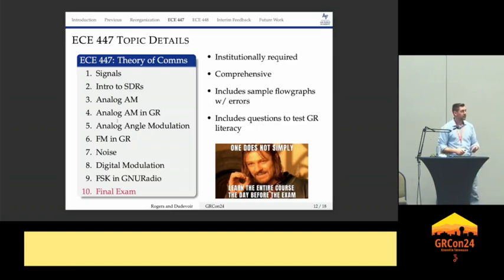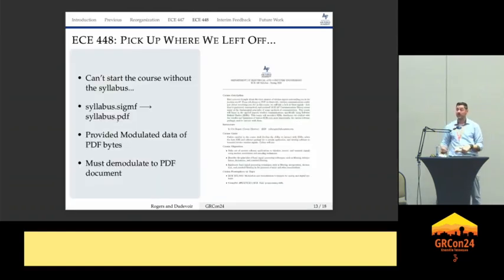Oftentimes what I'll do here in the final exam is put in some flow graphs with common errors, right? Sample rate mismatches between blocks, blocks that aren't connected, things that they should pick up along the way. That's my way of testing to make sure they have GNU Radio literacy, because when they decide to take the next class, we're going to pick up right where they left off.